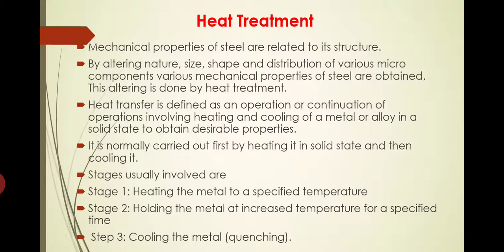Heat treatment is a simple process. During the heat treatment process we will heat a particular steel component in its solid state itself. We won't let it go into the liquid state. Within the solid state we will heat it, and after reaching the required temperature and maintaining it at that temperature for the required time, it is allowed to cool in a particular environment. That cooling rate will decide which property and which structure we finally have. By studying this we will have a clear idea at the end of this presentation.